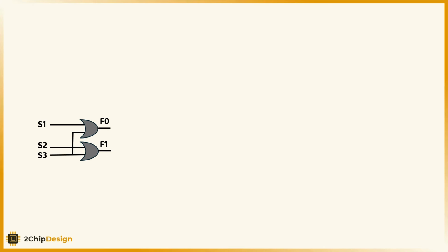To prevent this, we need a locking mechanism, one that says the race is over, we have a winner, ignore all other inputs. To achieve this, we will use flip-flops to store the winner and ensure the value doesn't change. In this exercise, we'll use the D flip-flop.